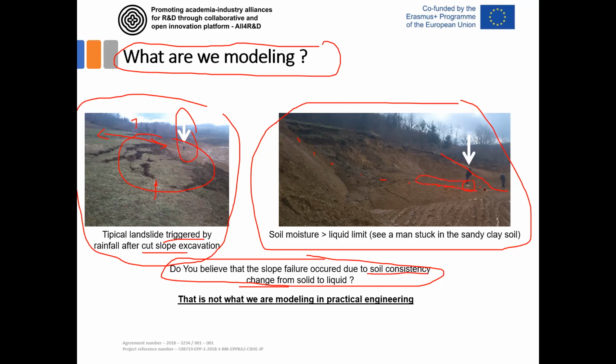If you look at the surface, you'll practically see a liquid soil, and that's why people who look at a failed slope, a deep-seated failure like here, first assume that after some heavy rainfall, water filtration occurred in this material at some depth of 5, 10, 15 meters, and that the soil became liquid due to water moisture and water level increment.